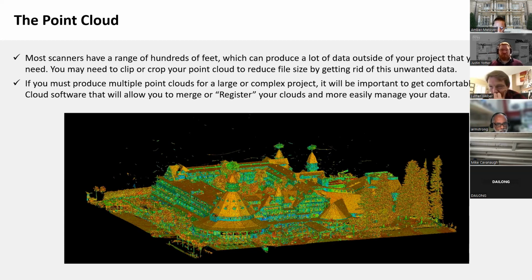If you must produce multiple point clouds for a large or complex project, it will be important to get comfortable with point cloud software that will allow you to merge or register your clouds and more easily manage your data. And since, much like the traditional method of sketching and measuring, properly scanning a structure takes lots of practice to do correctly and efficiently.